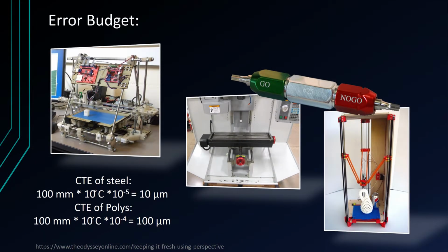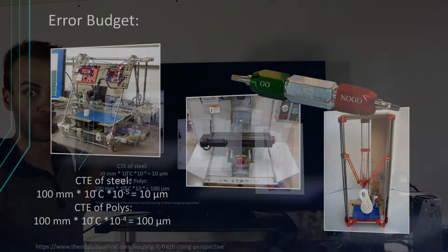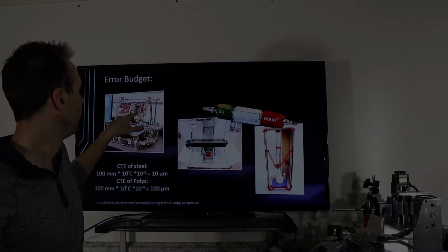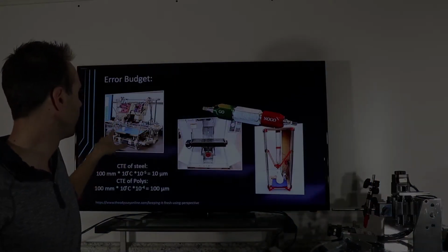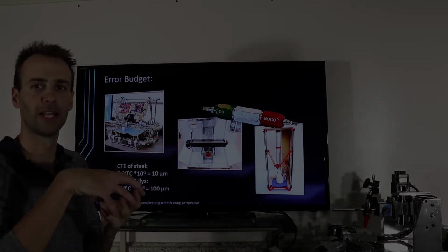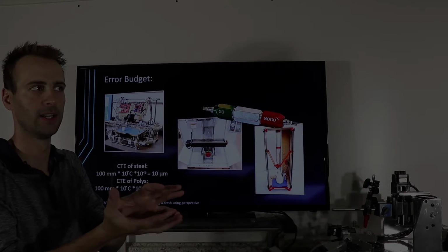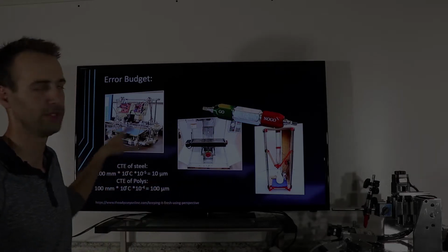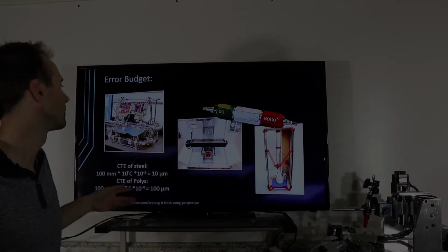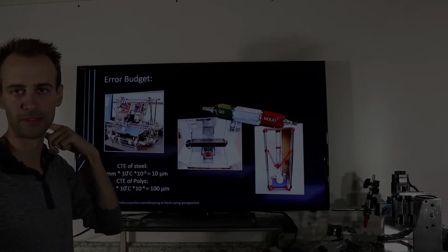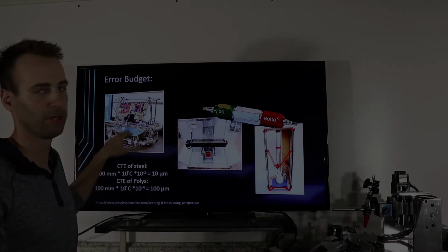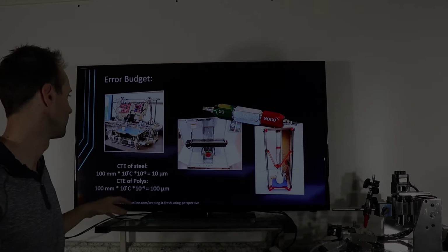Look, they put all of their driver electronics right on the machine. And where are their stepper motors? They're mounted to plastic. So this giant heat box is mounted to a plastic part. Again, if you're just doing pictures of your face and stuff, maybe that's fine, okay? But I wouldn't try to push any precision on a machine like this.